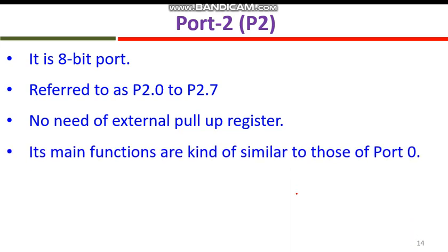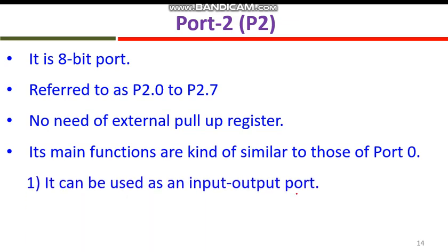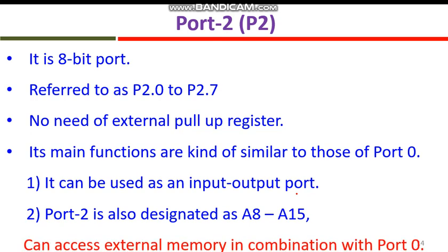Its main function is similar to port 0, so it can be used as a simple input output port, or can be used as an address port, that is A8 to A15. A0 to A7 are used by port 0, and A8 to A15 are used by port 2, and hence it can be used along with port 0.